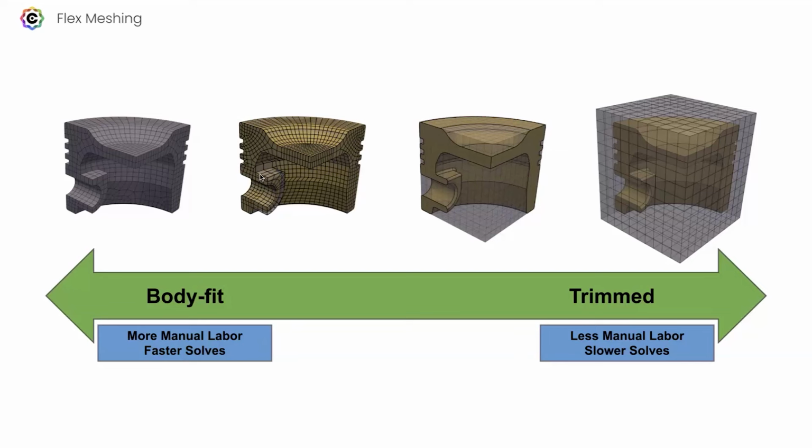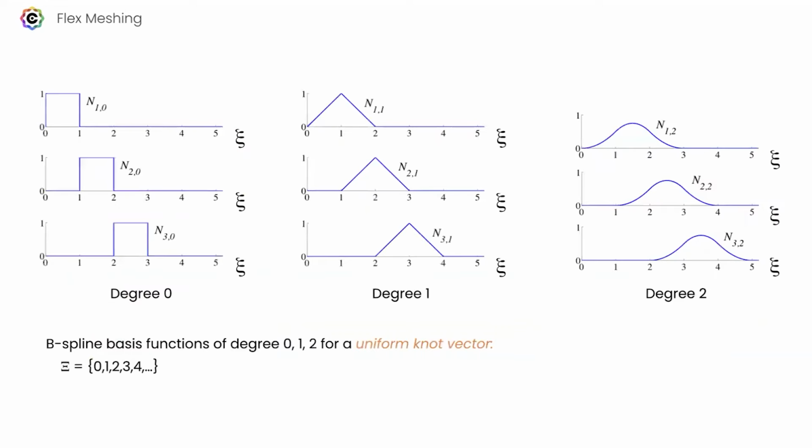Like in this case, you can see that these fillets are actually immersed. So there's no defeaturing that occurs, but the meshing itself is still simple because you can immerse these features. And then you can do something where you take the bulk shape and capture it in the mesh, where the rest of the finer features are immersed in the grid. So we call this flex meshing, and it's available in Coreform Flex now. And this is one of the key value propositions of what we're building, along with the isogeometric analysis technology.